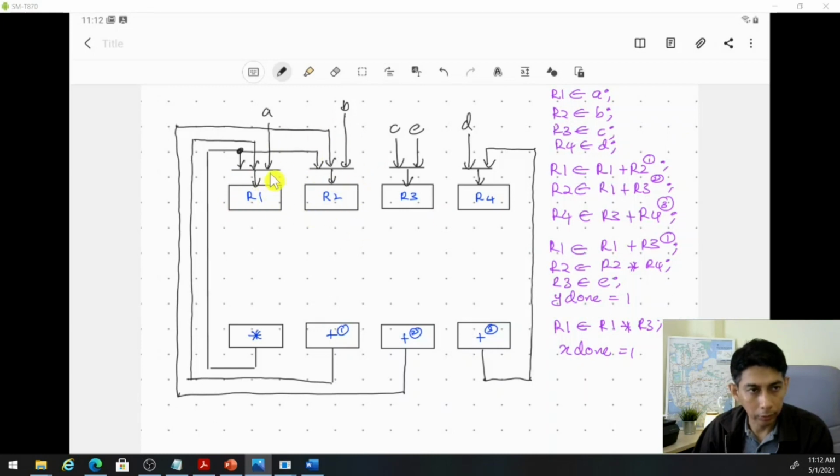All right. So this is 4 to 1 mux, 4 to 1 mux, 2 to 1, 2 to 1. And what about the connection between the output of the register and the input of the computation block? So again, we need to look at the RTL code. So for example, the multiplier, you have 2 operations here.